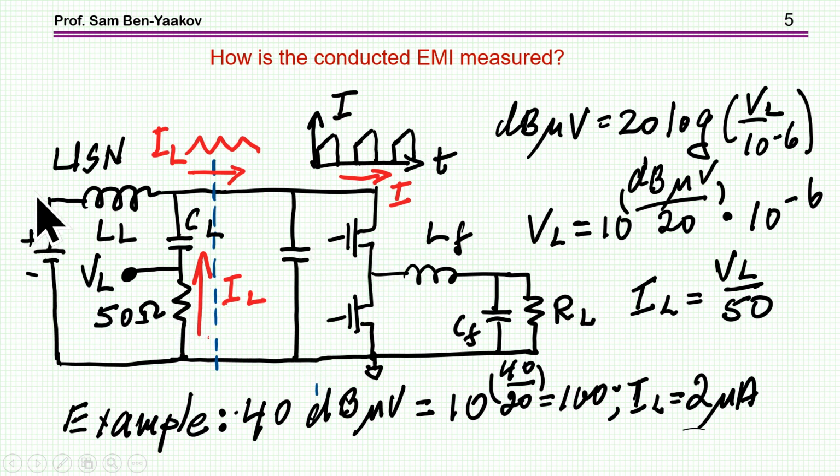We're using the so-called LISN, which is the Line Impedance Stabilization Network. Basically, it's composed of an inductor, a large impedance here, and then a bypass capacitor and resistor. And the idea is to capture the ripple here on this branch. I'm showing it for a grounded system without earth. In general, you'll have here actually three lines, so I'm showing it for, say, a battery operated system.